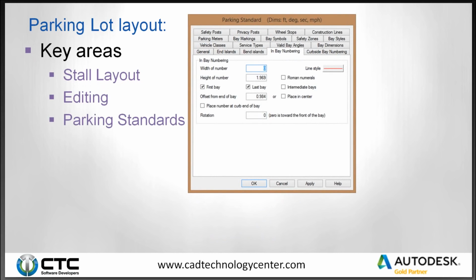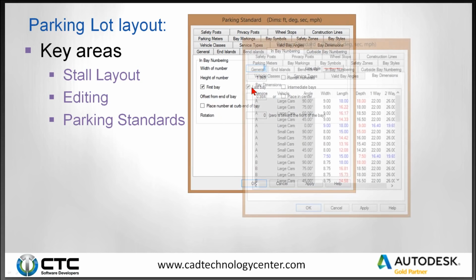And then there's parking standards within the parking lot layout. And the key on this one, as you can see, we have a whole bunch. Here I'm going to emphasize 3, the in-bay numbering. Right now I can number the first bay and then the last bay. And if I wanted to number each of them, I can actually do intermediate bays. My preference is to only do last bay.